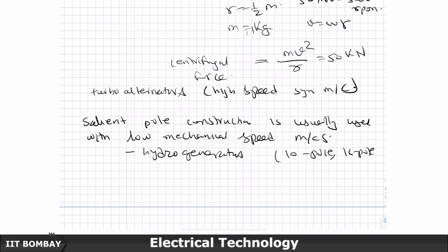detail. Some of these transformers issues we also come back and discuss there. Mostly we discuss phase shifting transformers, voltage regulating transformers, some of those things also we discuss. Current transformers and voltage transformers I had talked a bit. Usually that is discussed in much more detail in a protection course, because after stepping down like 1000 ampere to 5 ampere, we use it for sensing whether there are any faults or trouble points in the system, or the voltages may be 400 kV stepped down to 110 volts